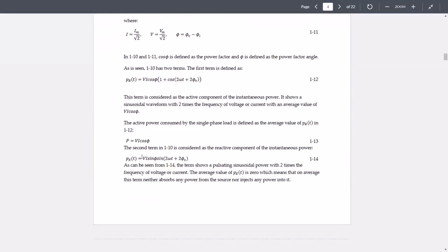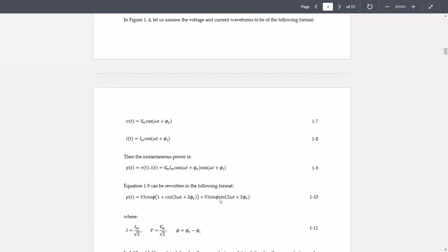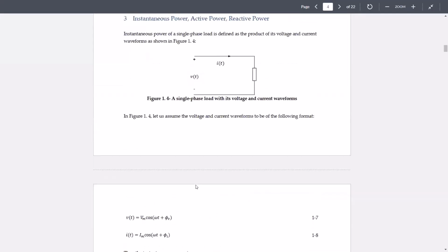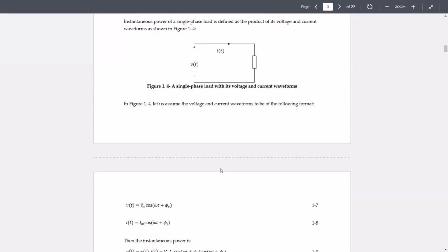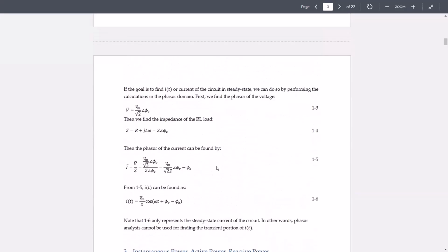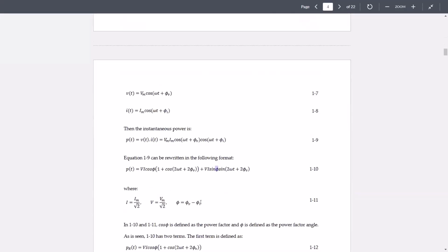But what about reactive power? So first of all, can you tell me when that reactive power happens? When you have an overall capacitive or inductive network. Because only in that case is when, look at this phi. If this sine of phi is 0, it means that phi would be 0, right? And what was phi? Phi was the angle difference between the voltage and the current.